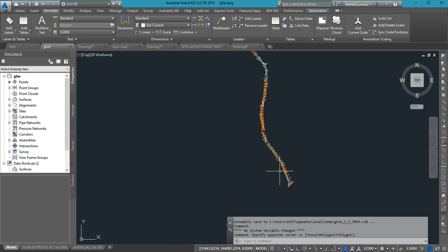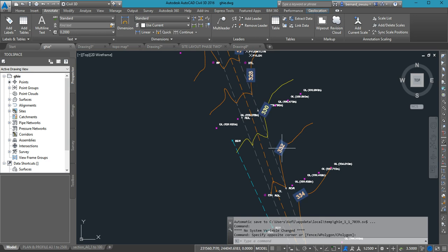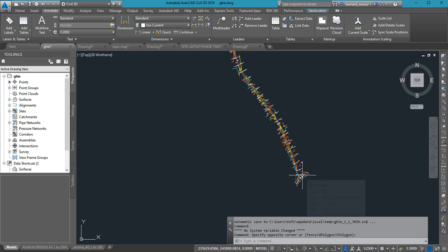So what we are going to do is define our design center line. The existing road that we have, if you remember, the surveyors also picked an existing center line, but that's not what we are going to use. We are going to define our new center line. It means that our new center line may not necessarily conform with the existing center line. Please, are we okay? And in putting in your center line, you want to, as much as possible, minimize property impact. Please, are you okay?